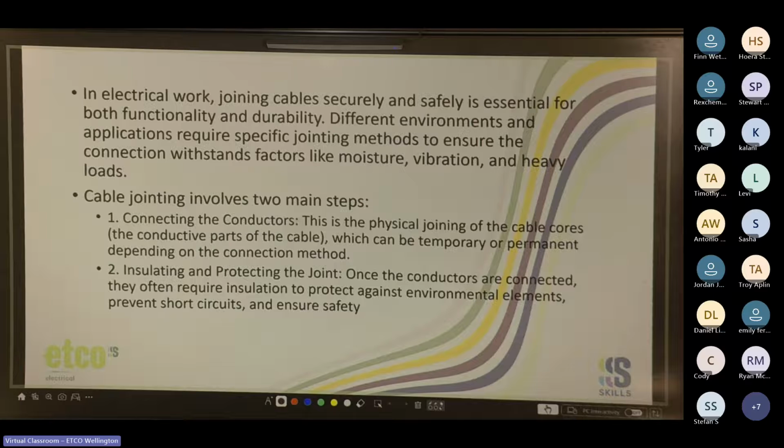So we're talking about permanent connections, like your crimps. Then you're using things like heat shrink, Raychem, or amalgamating tape. And if we're talking temporary, sometimes we're doing an IP-rated J-box with cable glands, or if it's inside a sealed junction box, preferably with a bit of tape and at least one or two cable ties to stop it coming loose and pulling out.